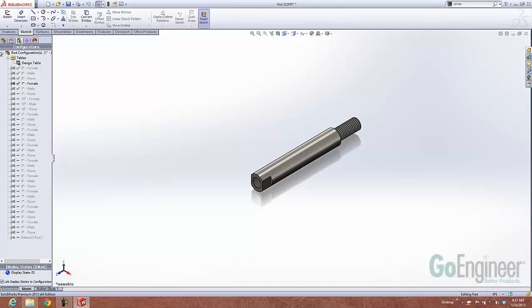But if there's certain configuration information that you want to store, that you want to be available when you open the file, you'll see we have these new options. You'll see these little check boxes and minus signs, as well as the ability to right click on something and say add a rebuild or save mark. And by selecting that, it puts a little save mark in here. When I rebuild, it will make sure that that configuration is rebuilt, so you don't have to switch to that configuration and manually rebuild it. Also, when you close the file, if you have that purge cache option selected, it's going to purge out all the configuration information except for the active configuration and the configuration that has the little save marks.